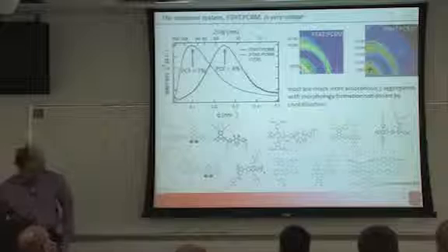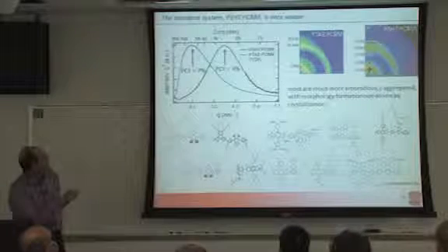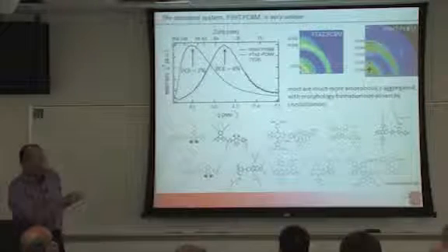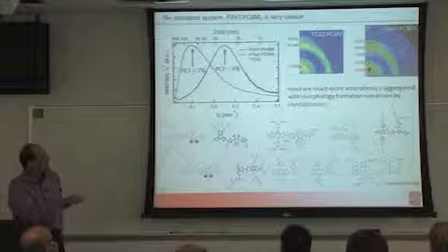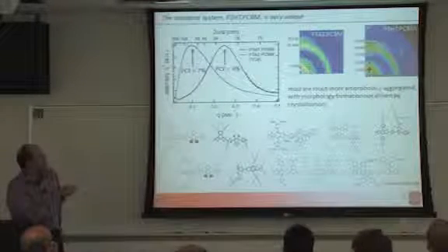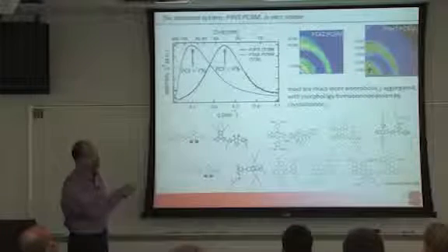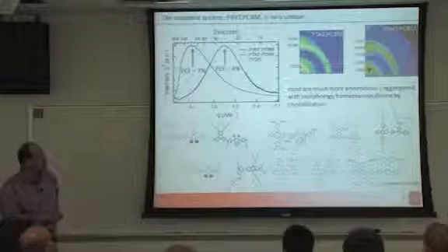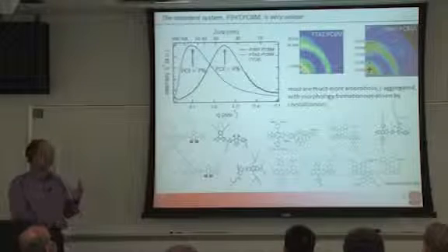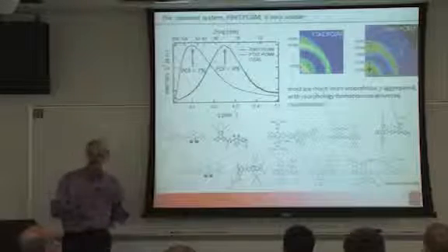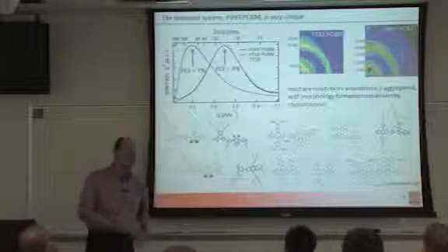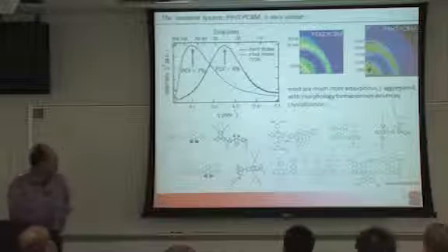All right. And here's just a summary that the P3HT is rather unusual. From the WAXS, I get relatively high crystallinity, and from resonant scattering, I get a Gaussian distribution. Most other materials, I get log-normal distributions because the phase separation process is different. In P3HT, the crystallization drives the morphology, and in the other materials, it's something else.